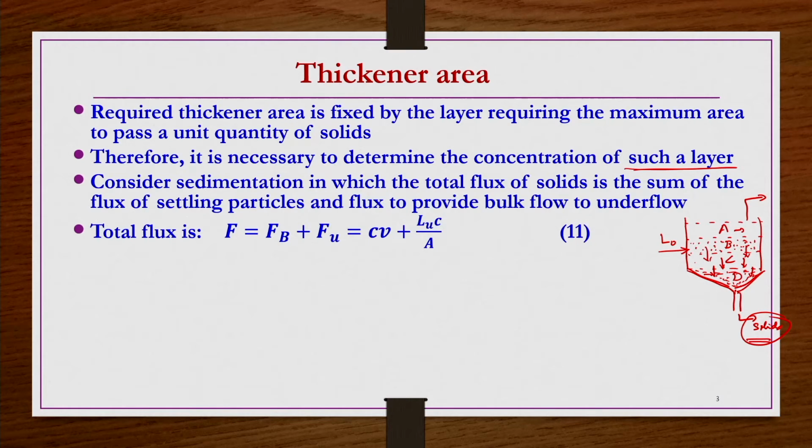Okay. If you are obtaining the flux at theta equals 2, because now the solids are continuously settling until a final, total or almost complete sedimentation takes over. Until that point, solids are continuously settling, and at each layer, at different times, the solid flux is different, right. So, if you calculate this solid flux at different times, then you can have F versus concentration information, because the concentration of this layer is also changing with time, right.